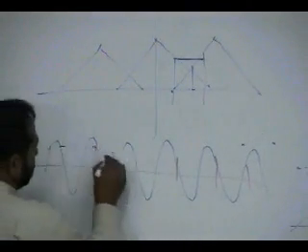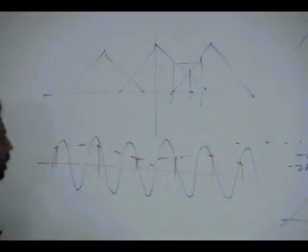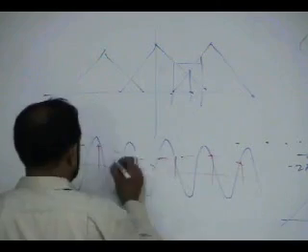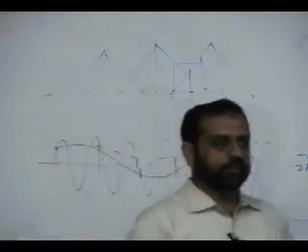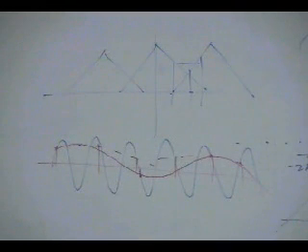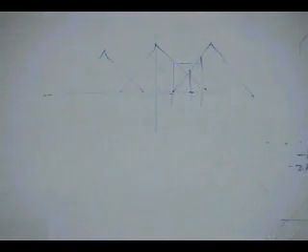so this is whatever, you will not get what it really is. I think it will be something like this. It will be a slowly moving sinusoid. So that slowly moving sinusoid which is already there will be corrupted. This is aliasing: if you don't sample fast enough, the fast moving sinusoid will be mapped to a slow moving sinusoid and will corrupt the signal. Interesting is what happens if you don't have that slow moving sinusoid. This is very interesting.